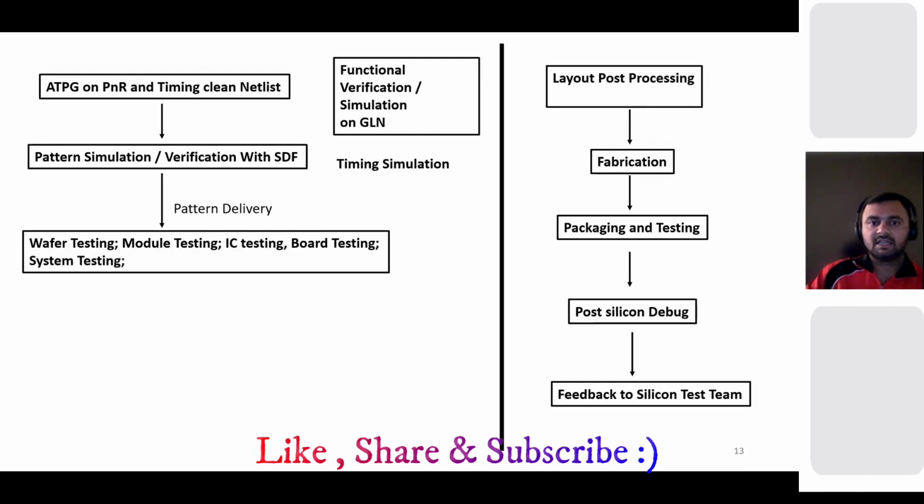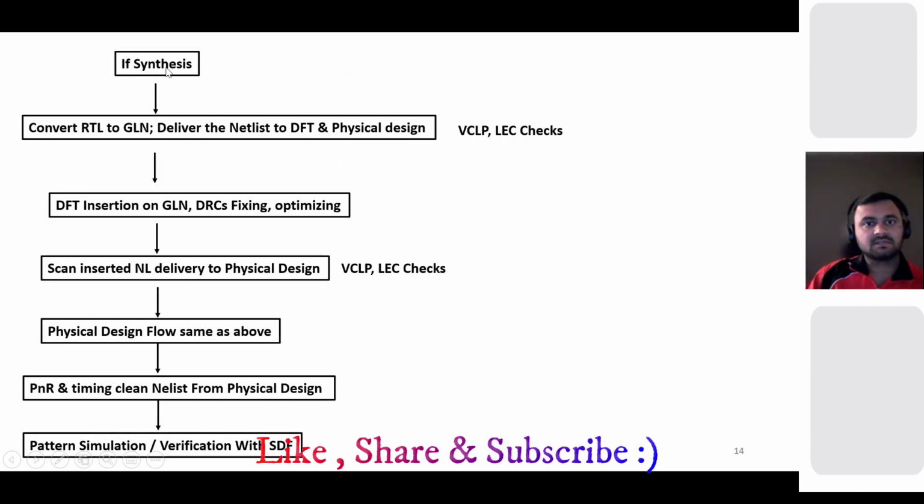So till now we were discussing the RTL flow, but suppose now we have the synthesis flow in some company. How it is done is, the RTL team directly gives RTL to the synthesis team. They will not give it to the DFT team. From there, they will directly synthesize it, convert RTL to a gate level netlist, and deliver the netlist to DFT and PD. And again, they will do the VCLP and LEC checks.